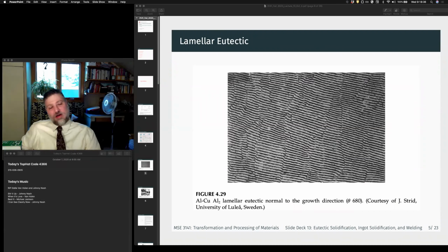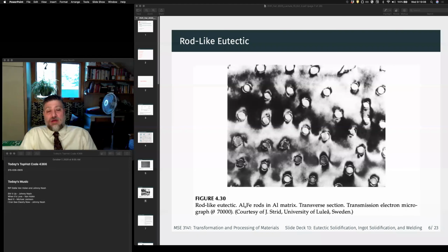For the image, this is, again, a really bad way of doing micrographs because I put this in the presentation at a different scale than what it's printed in the book, so the magnification's different, and then you're looking at these either printed out or on your screen, so it's at a different magnification. So that's why we always should put proper micron bars in our images rather than a magnification value. This is a TEM image, so this is at a much finer length scale than the lamellar structure, right? And obviously the volume fraction of the beta phase in the rods is smaller. Right.